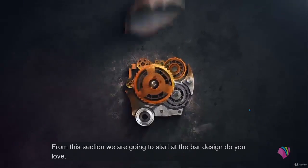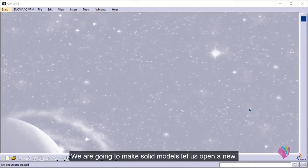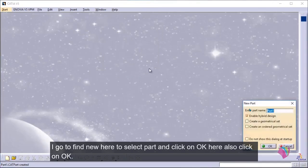From this section, we are going to start the part design module of Catia. We are going to make solid models. Let us open a new file. I'll go to File, New. Here we'll select Part and click on OK.